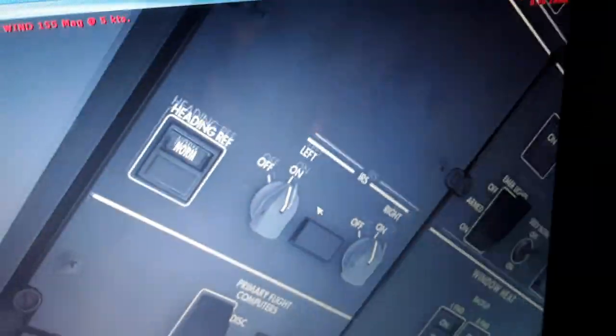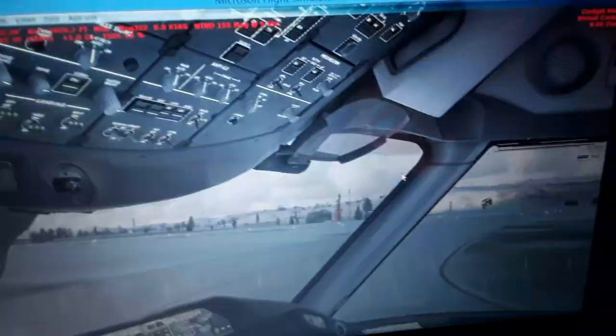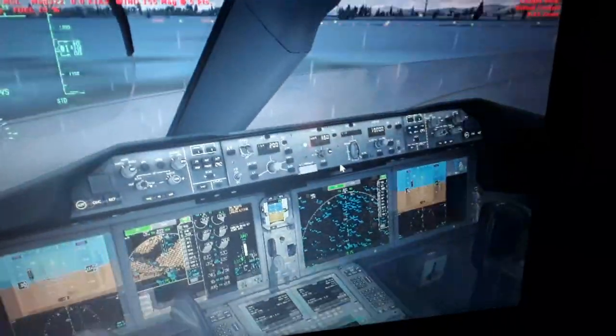As I told you, it's next to the air data computer above the electrical, and we have also flight control surfaces. So in the Airbus you can make turns like 2.5 G left and right turn and 67 degrees maximum using the side stick, and also you can climb like 30 degrees and descend minus 15 degrees, and we'll have climb like 1.5 G and descend minus half G.